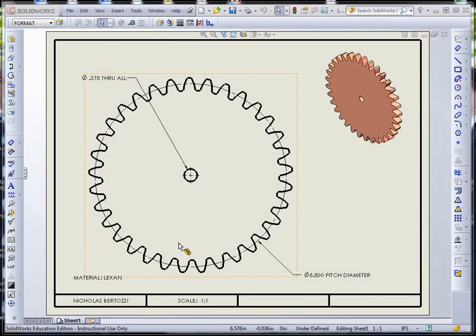So we'll end up with a gear that looks like this. Again, here's the pitch diameter, 5.5 inches. The pitch diameter, remember, is a very important diameter. You can't actually see it on the gear, but the pitch diameter is used, for instance, to determine the center-to-center distance between two gears. Two gears will rotate as if they were friction cylinders rolling at the pitch diameter.